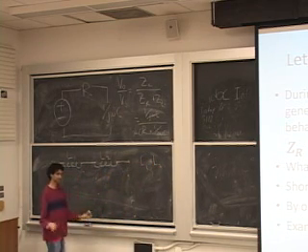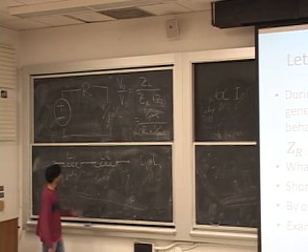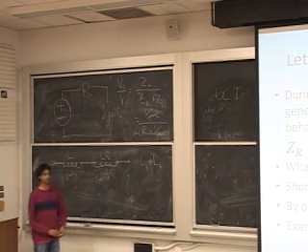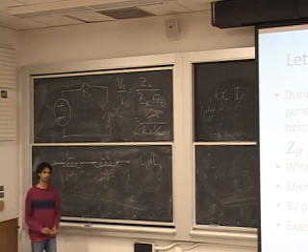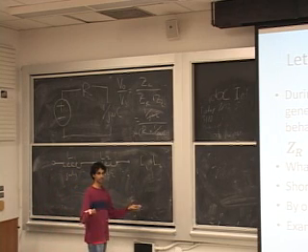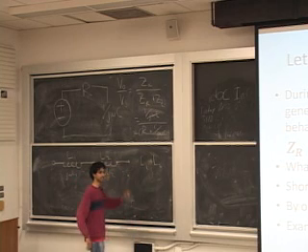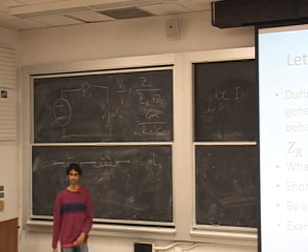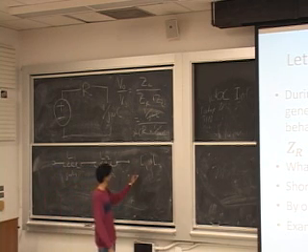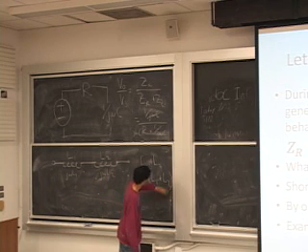Now let's look at the impedance version of this. Now I have j omega L1 and j omega L2. The impedance of an inductor is j omega L. Since I know these two inductors are in series and their inductance is L1 plus L2, the impedance of this whole thing should be j omega times (L1 plus L2).